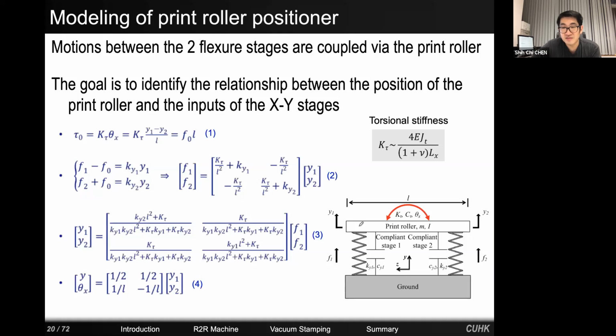So then we model the dynamic system. Basically F equals MA, but then we have multiple systems. The 2 degrees of freedom system, if we are looking at the roller as an object and 2 supports. Okay, so we can decouple the other direction, which is moving out of the plane. This will simplify the model and it's reasonable.